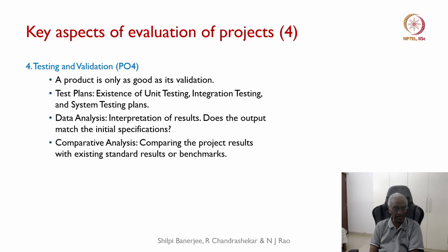Okay, you must create test plans right from the beginning. That is, once you complete the block diagram, you start saying who will test and what is the test procedure that you want to follow to prove that. The test plan itself will have to be created right at that stage. And then you should also look at what kind of data analysis that you would do.